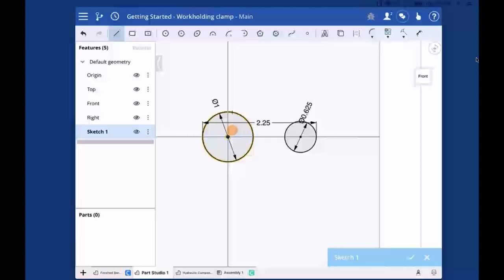Notice that as I use the precision selector, I move my crosshair down over that circle, it highlights, indicating that it's attaching the line to the circle. Right? Let go. We'll attach it here. If I move it to just the right position, you'll see it actually snap to tangent. And there's my line. Right? So I have a line attached to both circles and tangent on one end.